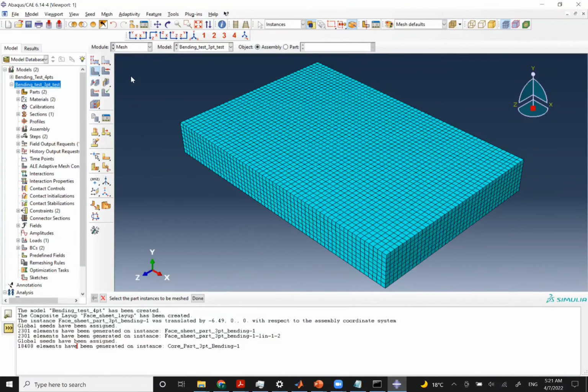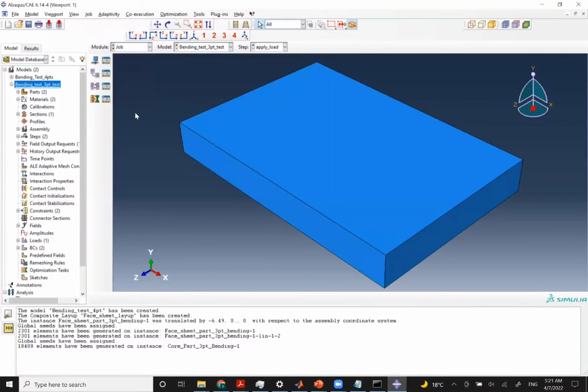So now we are done with the element, and we're kind of ready to go, hopefully. So we set our part, we set the properties, we finish with the assembly, we set our step, interaction, yes, load, yes, mesh, yes, and then let's go to job.